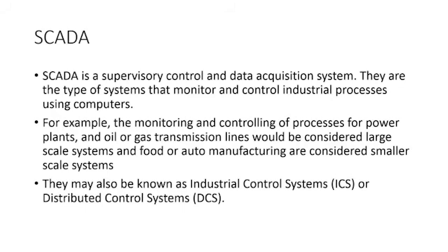If they need to monitor those lines, or if they need to open a valve or close off a valve, the management station talks to a controller, a PLC controller, a programmable logic controller that does whatever it is we tell it to do, or whatever it's programmed to do, if we hit a certain button on our SCADA system, on our management system.